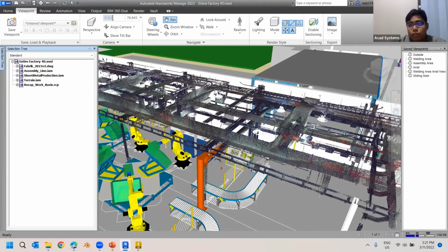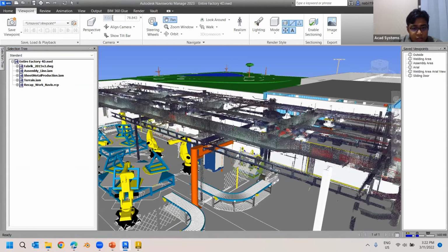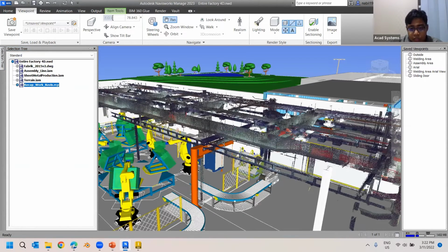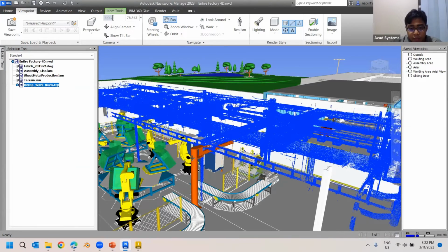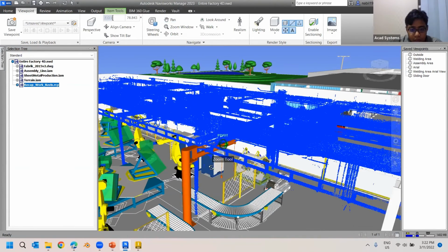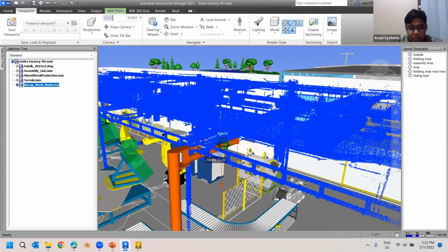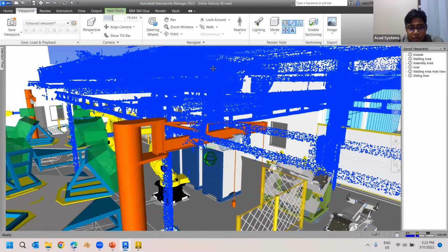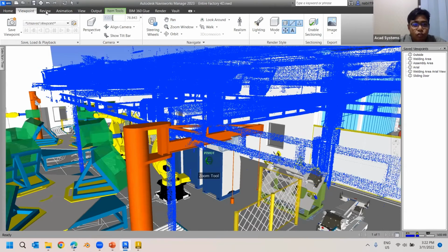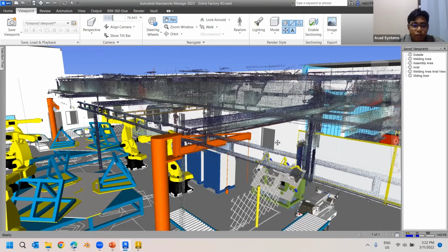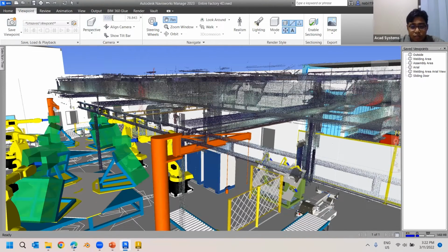For example, if you have a 3D scanner that you would like to include, Navisworks also allows you to add 3D scanner objects inside of Navisworks, so you can do product collaboration from here. So you can see we have this ReCap work, which is this van over here, and then we also have this item over here. If you take a look, there are some clashes, right? So you can use Navisworks to do some review and check whether there are some clashes, some interference.